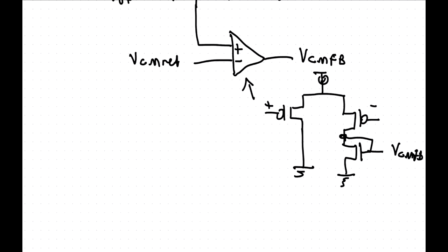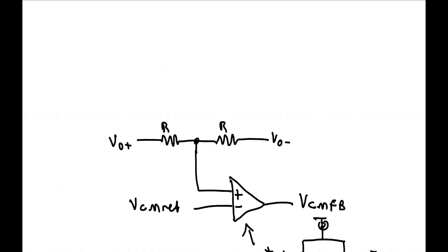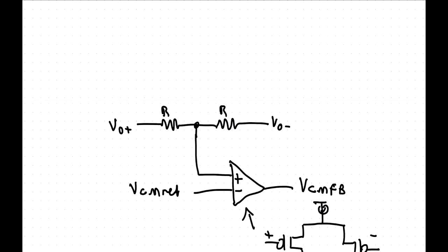With a PMOS input pair here, we've got to have a voltage which is kind of lower than mid-range anyway. We lose a threshold voltage this way. So if we use an N pair to shift it up first, we can shift it down again. So we're not actually losing. We're losing a threshold voltage of swing at the output, but it's not too detrimental.